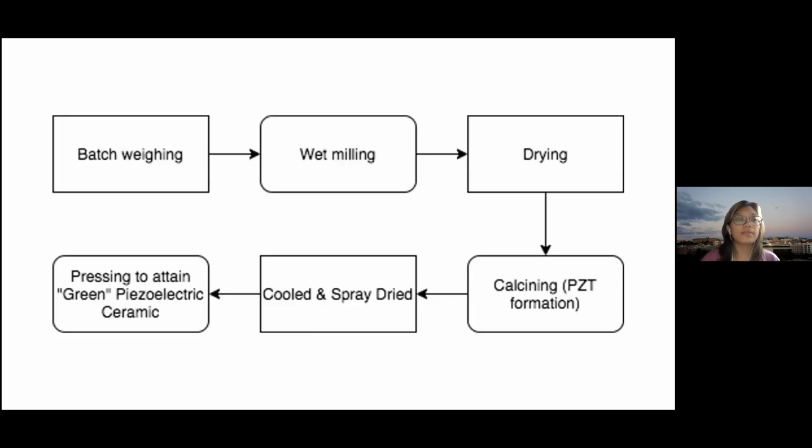So this is the manufacturing process in a more detailed flowchart version. The process of manufacturing PZT powders consists of 6 distinct unit operations shown in the figure. Throughout the world, high purity raw materials are evaluated, selected, and sourced. Material activity and limits on specific deleterious impurities, in addition to purity, are used as selection criteria. After each material has been chosen and approved for use, it is precisely weighed and transferred to wet mills according to the formulations being manufactured.